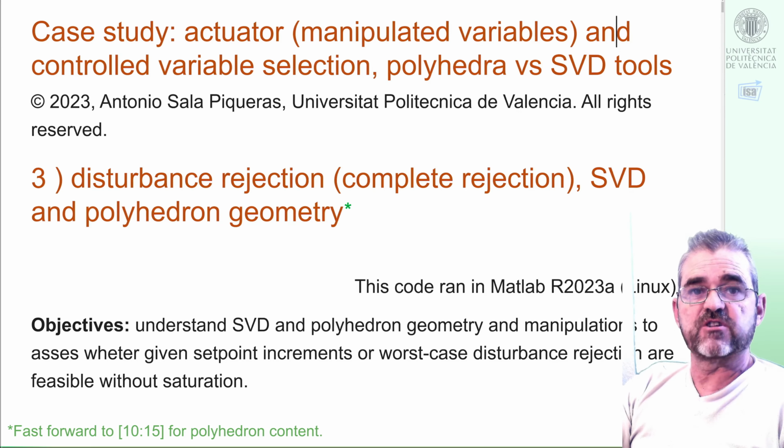These are our limits in the incremental manipulated variables, non-symmetrical, and in our disturbance rejection problem, we will assume that disturbances in absolute units, non-incremental, lie in these intervals around this operating point, so that the incremental displacements of the disturbances will be in the range from 0.8 to minus 0.6 in the first disturbance, and the second disturbance will range from minus 0.65 to plus 0.4.